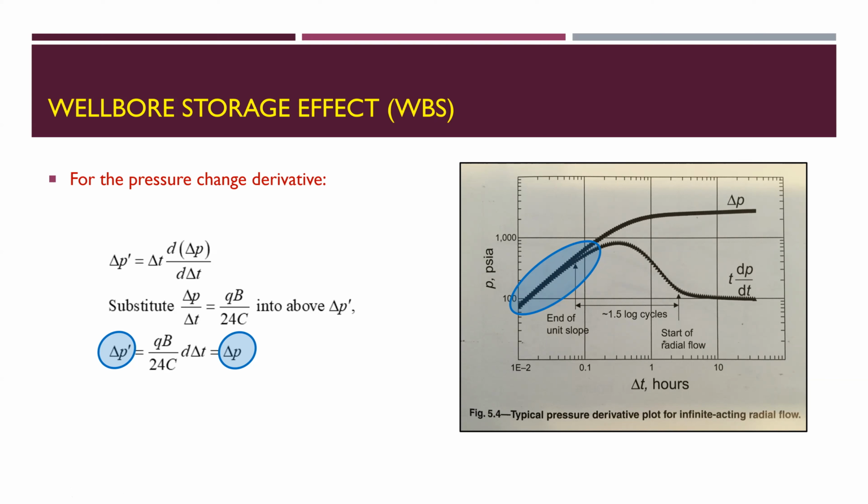And this is the benefit that you can receive if you are now making a plan for a well test. One factor is the timing or duration, how long the build-up will last. First, you need to see what about wellbore storage and what about transition. So this is dead time, dead information. We don't receive any valuable information if you stop at this line here. So you have to consider a longer period of time if you are already anticipating wellbore storage with a transition period like that.